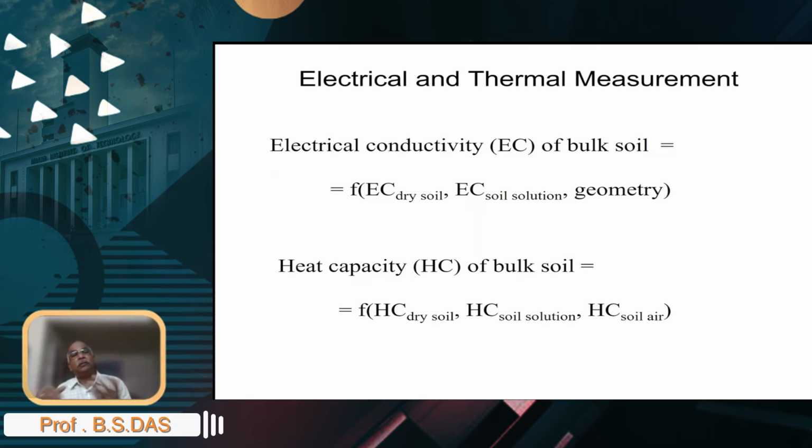They really contribute to the electrical conductivity. The electrical charge, which is basically your cation exchange capacity, for a given soil, of course, remains constant. So if you do the calibration, it should be all right. So that relative change in the soil wetness you can still measure using very inexpensive electrical conductivity probes.